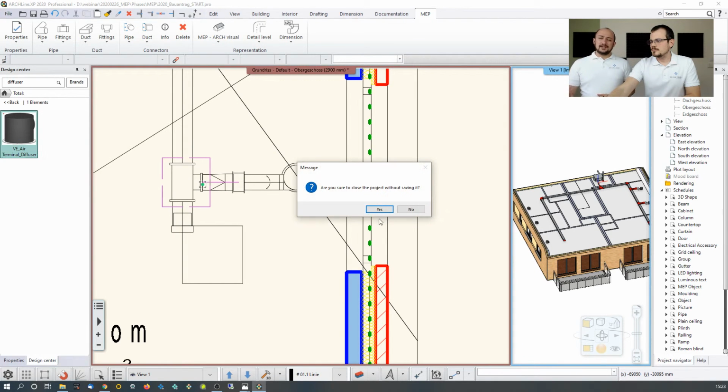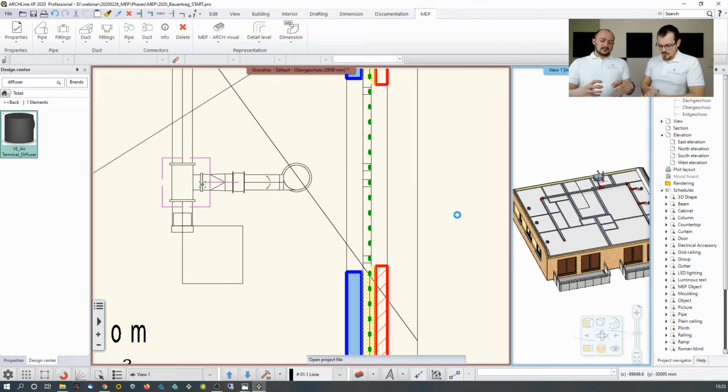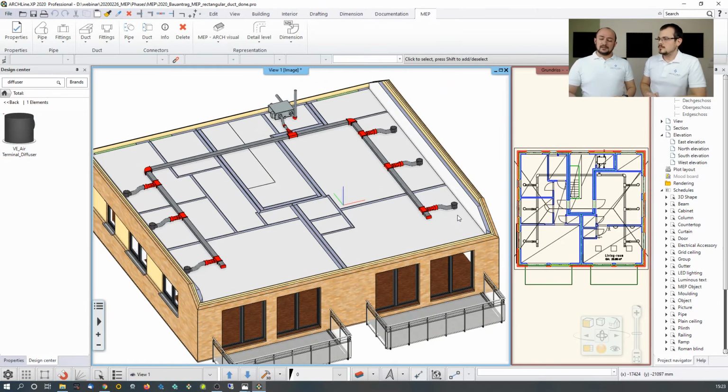Well, no worries. So what we need, when we create such a system, is to create the duct main system, the main path, and then set up these tiny parts that we connect together. When it's necessary we can bridge the gap in level using the reducers or the shape changers, the transitional parts, and those are all automatically calculated. That's the best part of this, that these are all automatically transitioned and connected together. We didn't calculate what the size is. The MEP designer did. We are just replicating. And we don't care about the airspeed or the moving parts. We just want to represent what we have on this model.